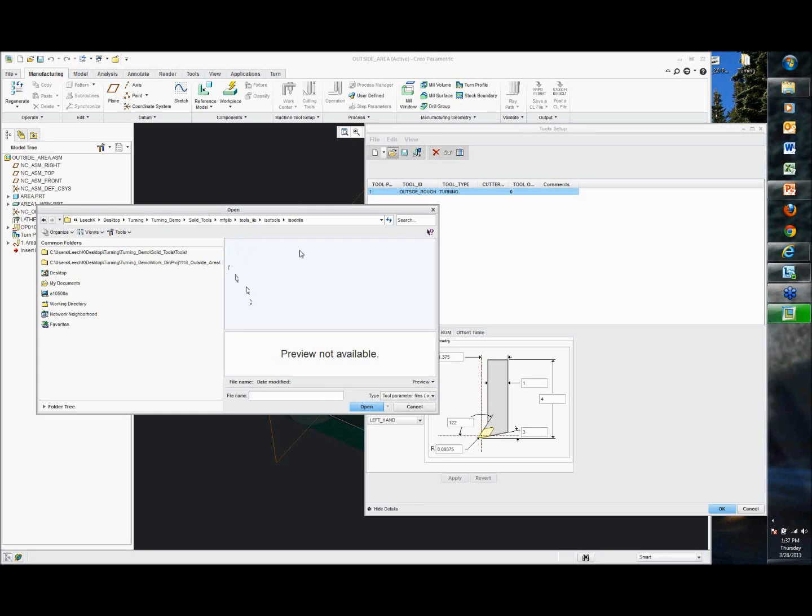So here's my drills. Well, that's what I'm wondering. If I organize them into folders, and then as I try to save, if we're working on aluminum today, stainless tomorrow, and steel the next day, these tools all have different feeds and speeds in the same tool that is saved back under the different materials.